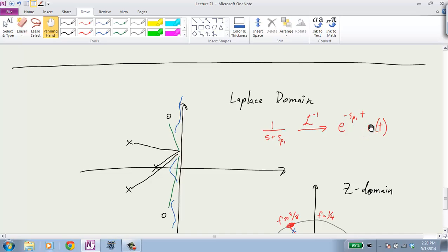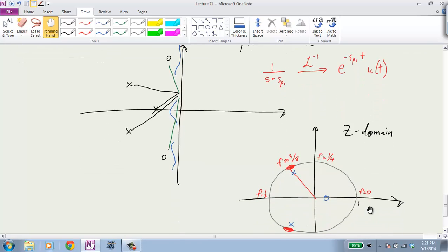You might call that a quick response. You might say the system is very responsive on a fast time scale, if the poles' real parts are very negative. Now, if they have an imaginary part, that becomes a sinusoidal oscillation in time. Okay, so they have some sort of resonance as well. I'm just trying to give you some intuition about how to interpret poles and zeros in a way that's meaningful.